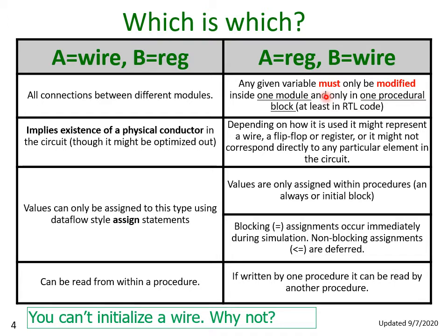In hardware, if you have multiple assignments to the same wire, and variables in Verilog sometimes do translate into wires in the circuit, but assigning multiple values in hardware, unless you're using a tri-state buffer so that only one gate at a time can force a value on the wire, you'll get conflicts and things like unknown values, at least in the logic simulator. So you really should only be assigning the value in one place.